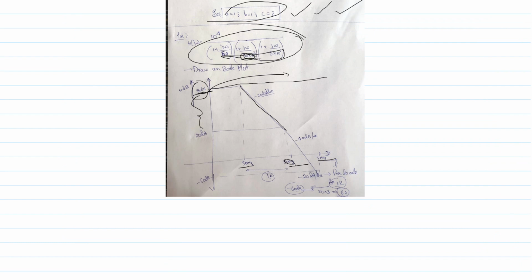For 1 decade minus 20, for 3 decades minus 60, so 80 minus 60. You might take 80 dB and consider 60 here, but that would be a blunder, because it is clearly mentioned that for one decade it is minus 20 dB. So here, with 3 decades, minus 20 into 3 is minus 60, so 80 minus 60, totally 20 dB.